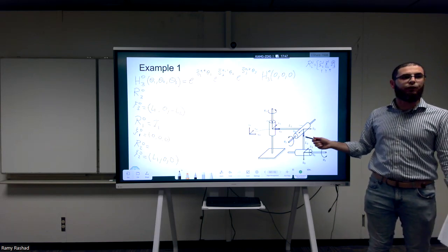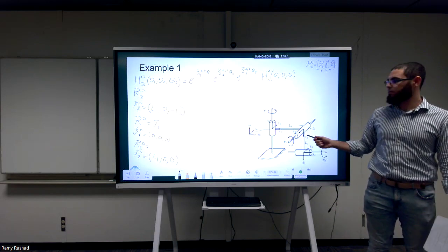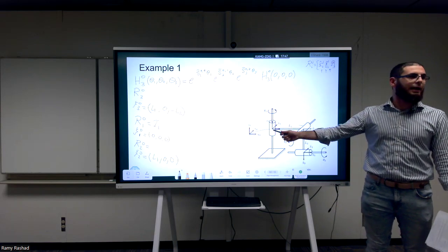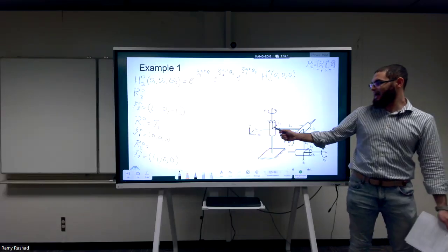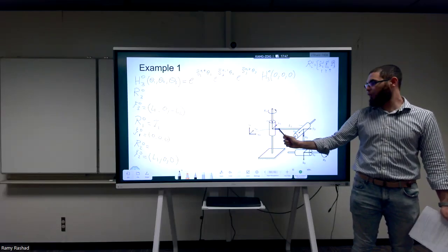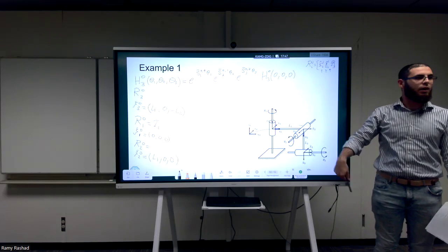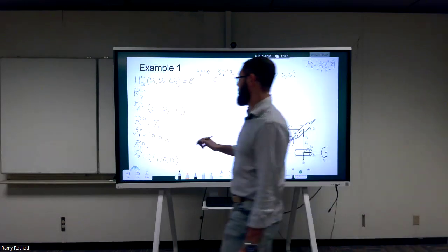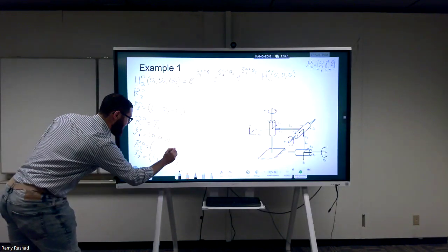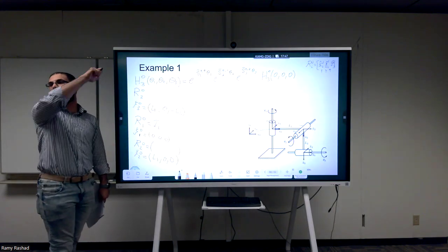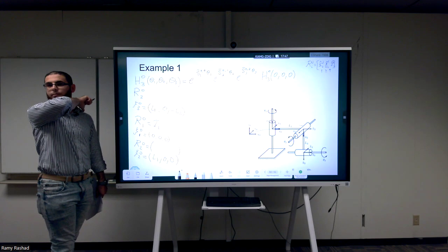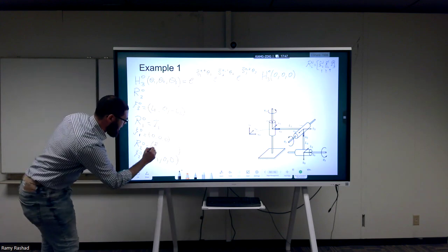It is the same as which frame? It's the same as which axis? As the minus z1 hat, right? So x2 hat is the same as minus z1 hat. Z1 hat is up, x2 hat is down, so they are minus of each other. So if I want to represent this as a 3 by 3 matrix, the first column here, which would be the x2 hat seen in the 0 frame, would be 0, 0, minus 1.